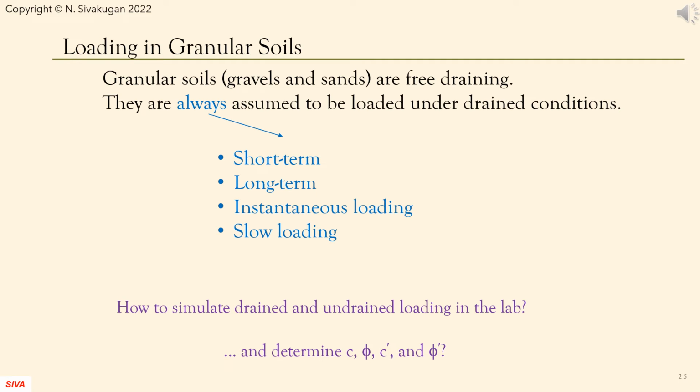Granular soils are generally assumed to be free-draining and hence analyzed in terms of effective stresses. Now that we have shear strength parameters in terms of total and effective stresses, how do we determine them? How do we simulate drained and undrained conditions for clays in the laboratory?